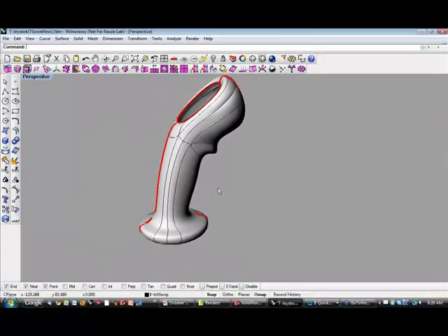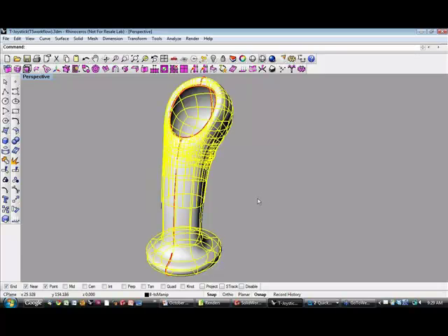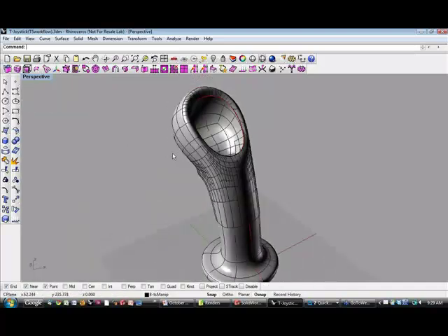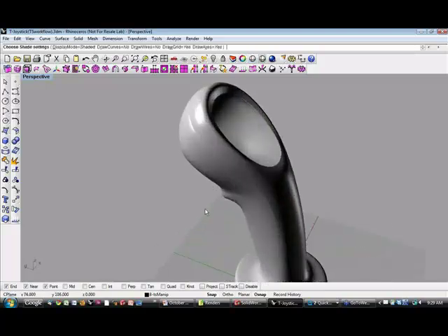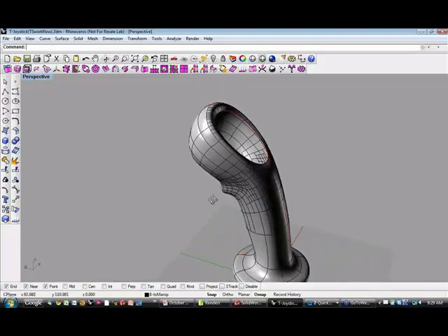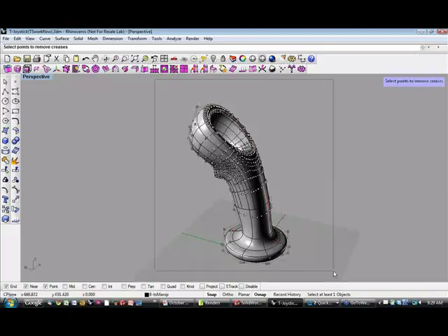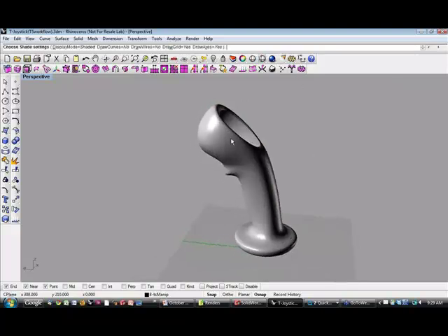Well, that's easy. We can just go back to Rhino, and let's undo some steps. So we go back to the T-spline model, and let me go back to shaded mode. So for instance, maybe I want to remove the crease in the T-spline surface. To do that, I'll just use the remove crease command, by right-clicking on the crease icon. And I'll select the whole model, so all the creases in the model will be removed. So you can see that's nice and smooth now.